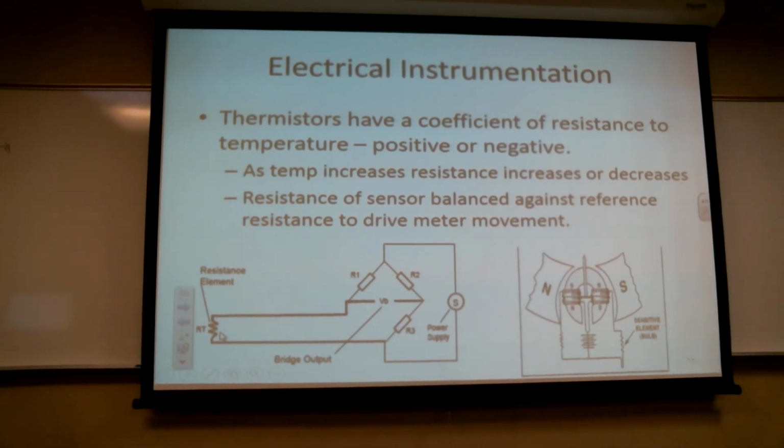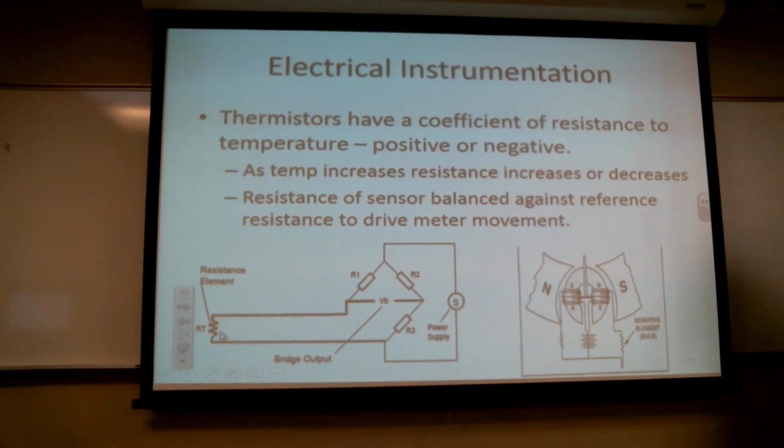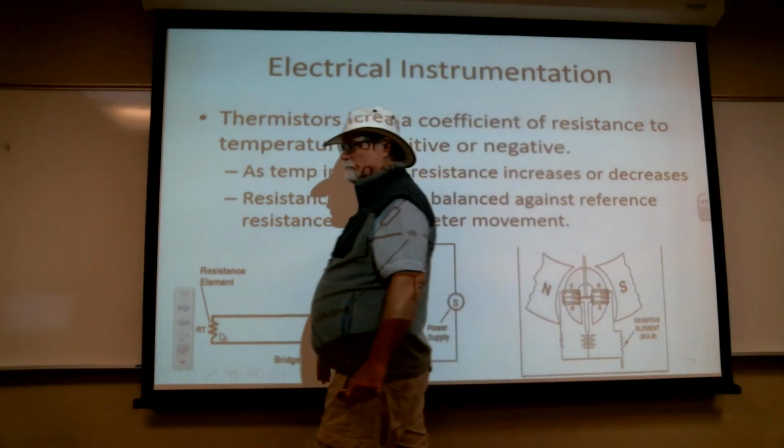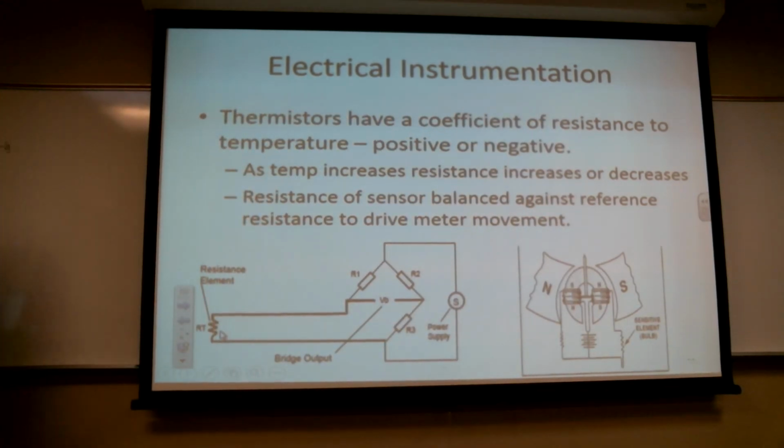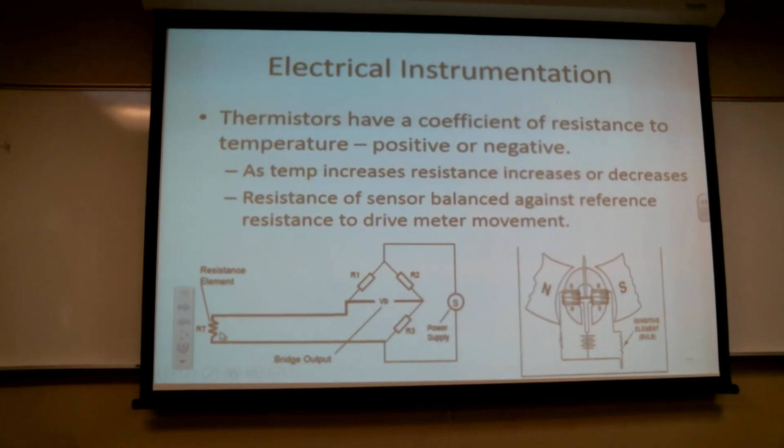There are a couple of exceptions, like an amp gauge, where we actually use a double wound spring and it holds it in the center. So reverse current causes it to move one way, forward current causes it to move the other direction. If you turn off all the current, the double spring brings it back to zero. It's called the d'Arsonval movement. Very sensitive instrumentation.